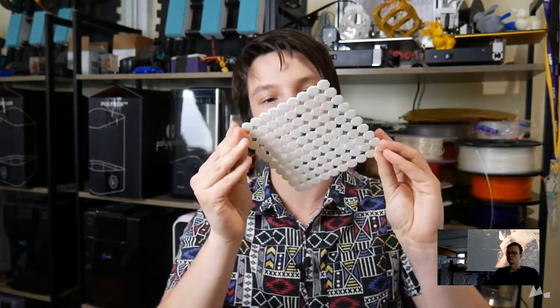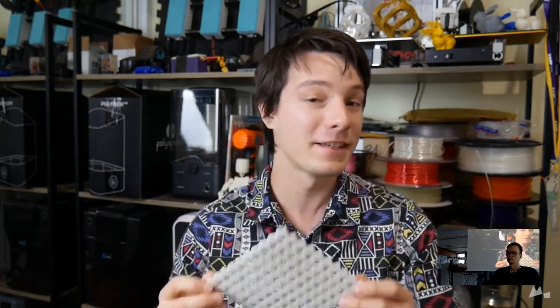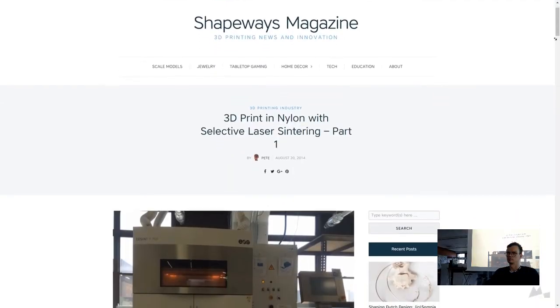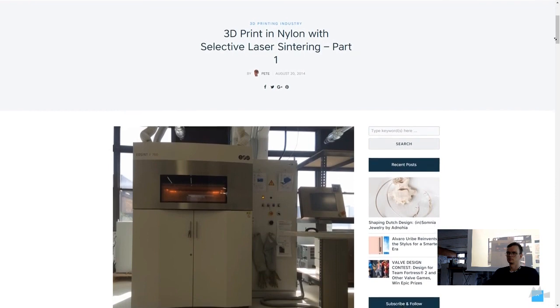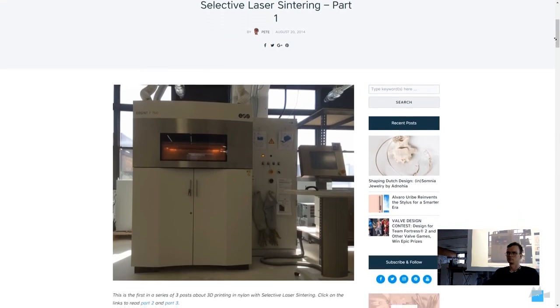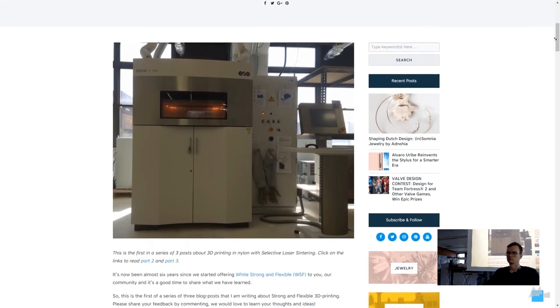So in this video, I want to go through and compare both the Formlabs Fuse 1 and the Sintering Lisa, as well as compare it to some commercial SLS prints like I have here, which I received through Shapeways. These would have no doubt been printed on an EOS system. The original company produced SLS technology, and an EOS SLS system costs well in excess of a few $100,000. So I'm going to compare the quality here, and I'm going to go through some advantages and disadvantages of the different technologies. Firstly, let's start with some numbers.